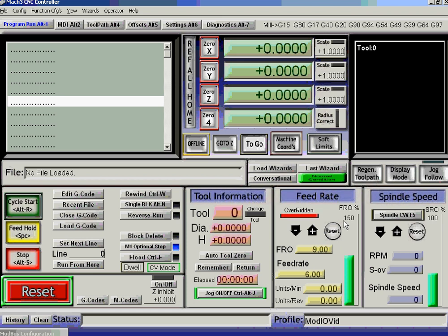all the way up, so I get 150% feed rate override, and I'm turning it down, and so it updates the DRO, and because it's a special DRO with a slider, the slider is going as well. So I can change my feed rate override using the analog potentiometer. Now that used to be possible, but required lots of VB script in a macro. But I think you will find that that is quite useful.